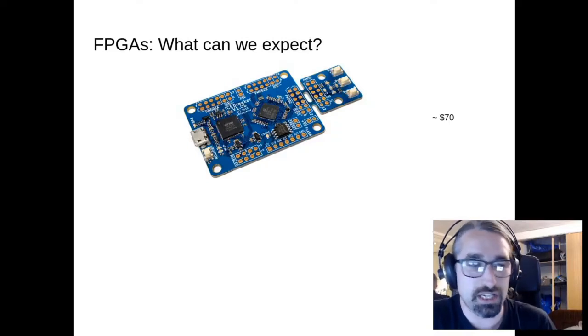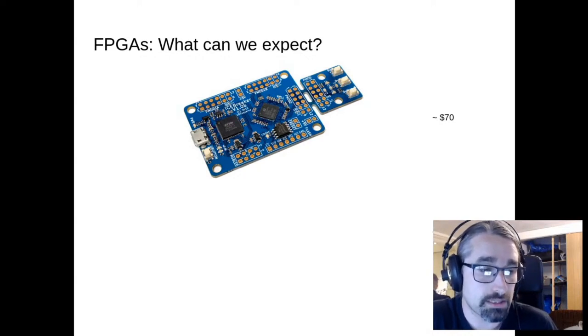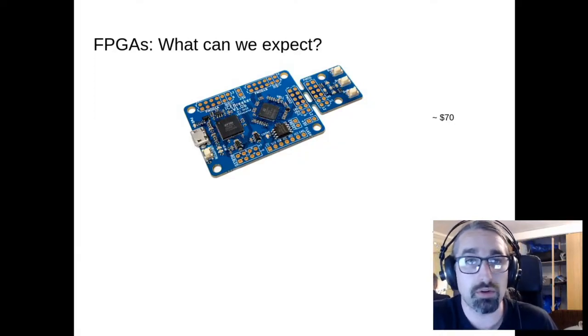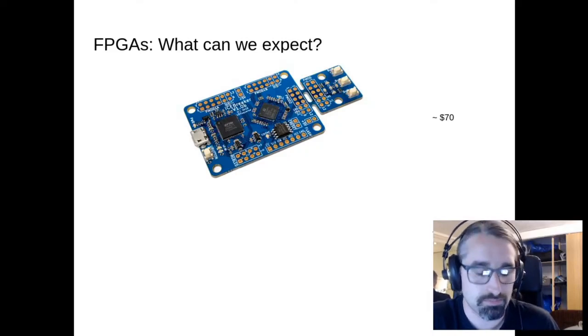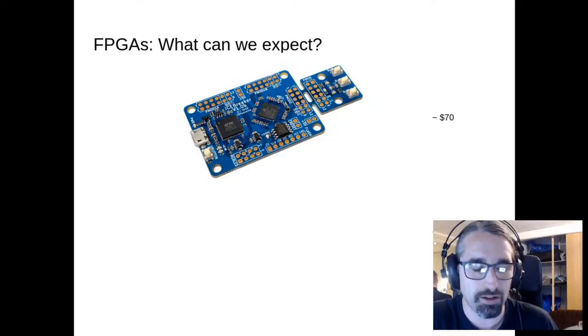How does it look on FPGA? Well, if you want to see a very simple one, this one is the Icebreaker, which is basically like an Arduino but with FPGA inside, so it's the same type of devices that you would be able to make, except this would be much faster. And if you want to make your own display controller, then that would be already sufficient for CRTC, for VGA or things like this. But of course, if you want to go with HDMI, that doesn't really work.